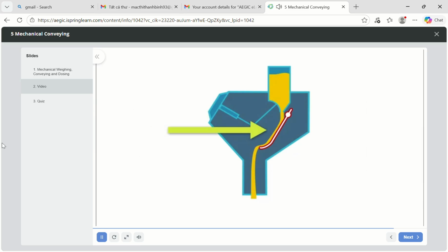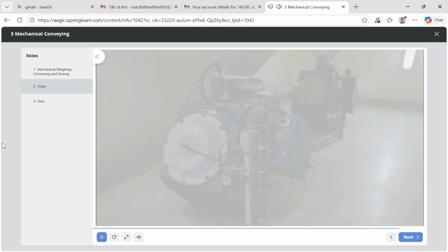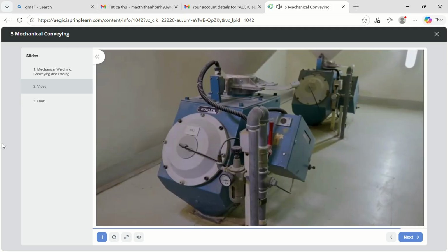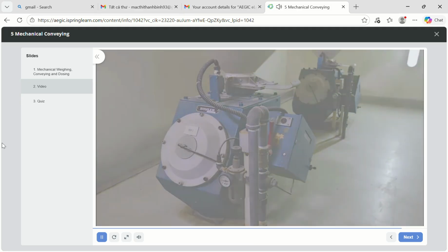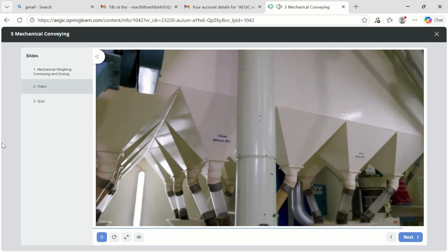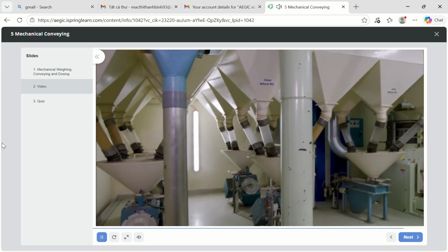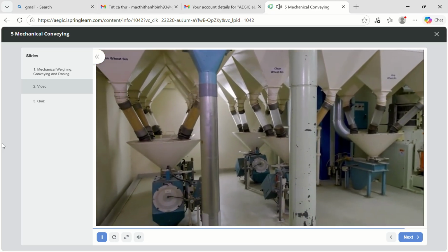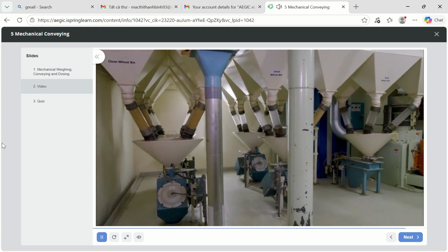Flow balancers use a deflection plate to measure the flow rate. A slide above the deflector plate varies the flow based on the target deflection. They are often used to dose out grain from wheat bins. They are less accurate than batch type or loss-in-weight type dosers.